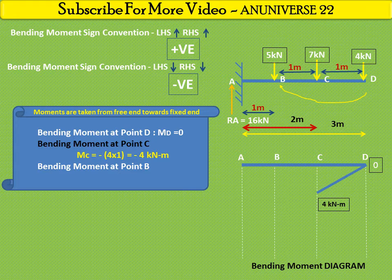The 7 kilonewton load covers a distance of 1 meter, so that is also negative, 7 into 1. So the bending moment at B is negative, 4 into 2 plus 7 into 1, equal to minus 15 kilonewton meter. On the bending moment diagram, the inclined line goes up to minus 15 kilonewton meter, a negative value.